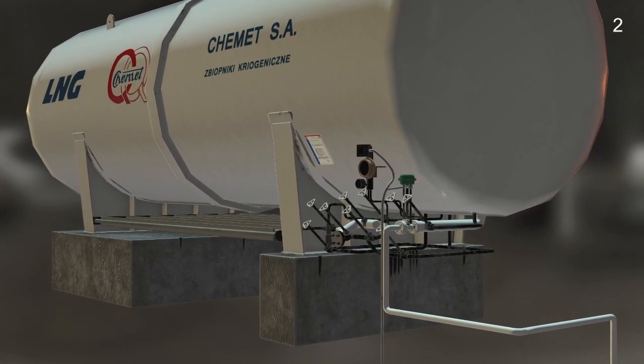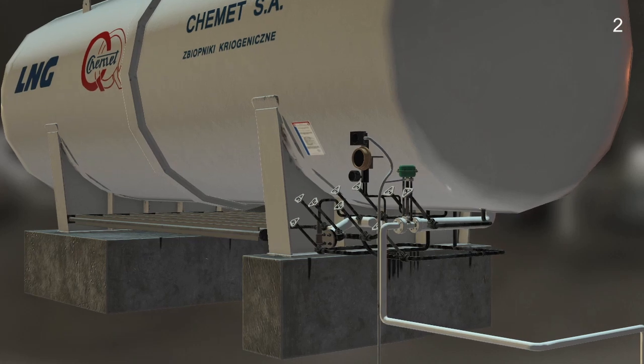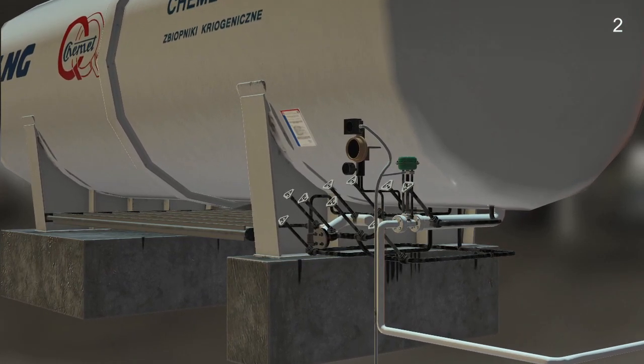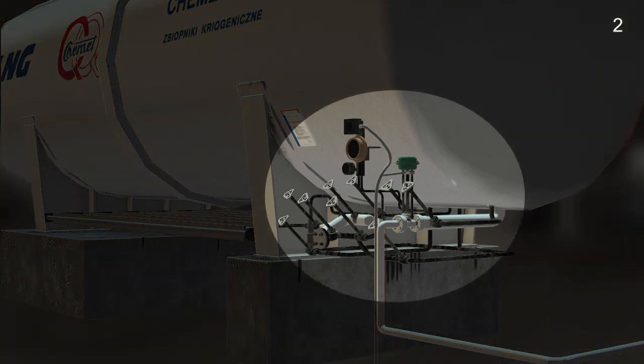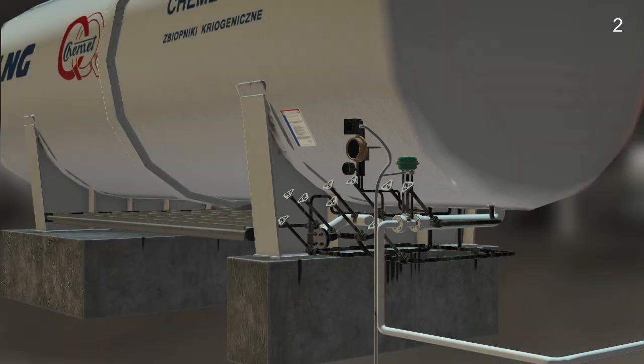A propane release will often cause ice to form around the release source due to a thermodynamic cooling effect that causes water vapor in the air to condense and freeze around the release source. Since propane is heavier than air, it will collect near the ground, creating a flammable layer, thus affecting the classification extents. The most likely source of release from the tank are the valve stem connections we see here. Let's use ExHAC to classify this propane tank.